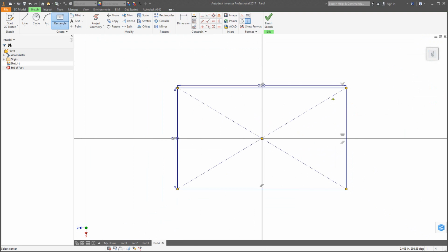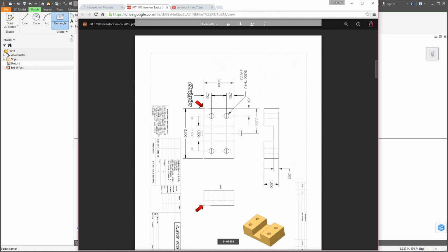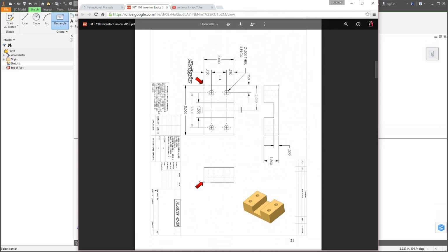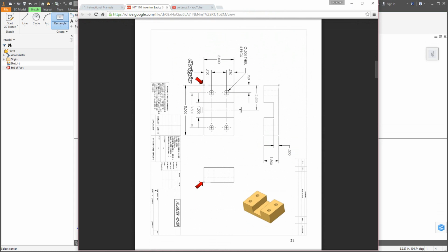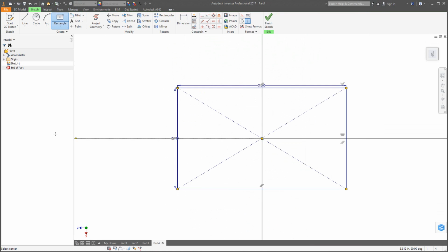And so with the length and width there, I'm just going to bring up the document and we'll take a look. And you can see it's 3 by 5. And then we have this, the overall thickness is 1.5 inches. So I'm going to actually use a tool here. I'm going to use the circle tool. I'm going to glide up around this area here. Be very careful. Don't lock your circle into the center lines. Stay away from the center lines. So I'm over here. I'm going to click. I'm going to drag out the circle. And this circle needs to be a 1/2 inch.